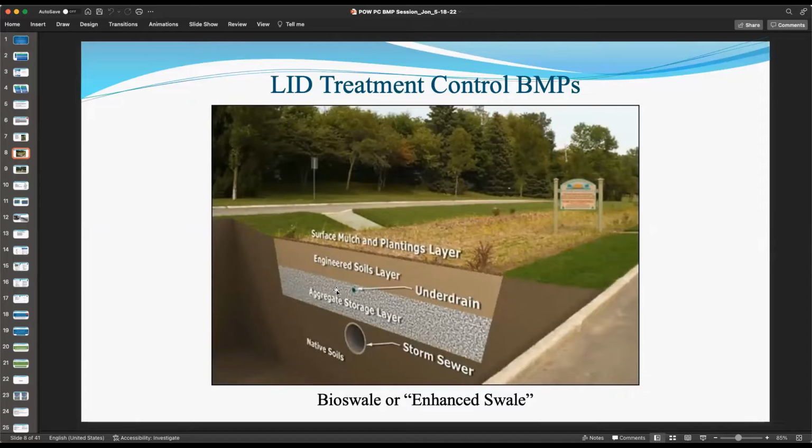So first off, one of the things you can do is design the underdrain system in such a way to keep the maintenance as low as possible. This typically is accomplished by, if this is a perforated pipe, you want to keep your perforations on the underside of the pipe below the midpoint. And that allows water to enter the pipe from the bottom, but reduces the chance that fine sediments are going to get into that pipe. If you put the holes on the top, more likely that you're going to get sediment in there.